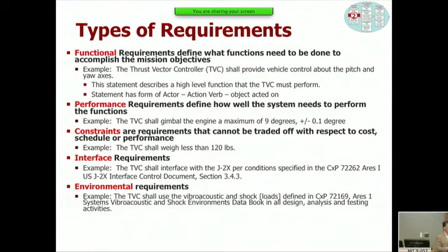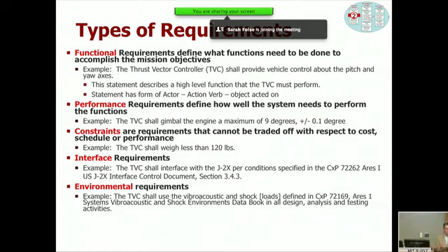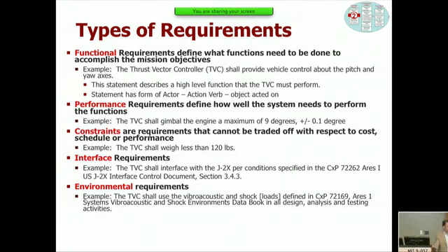So this is a big deal in practice, and at least in space systems design, a lot of these environmental requirements are of course driven by the space environment or the launch environment. If you're designing airplanes, whether you're flying in a small mountainous country like Switzerland or on the ocean off of an aircraft carrier, those are very different environments, and they're going to influence the design. You have to specify the operating requirement. The bigger the envelope that you make for the environmental requirements, the more complex the system will be.